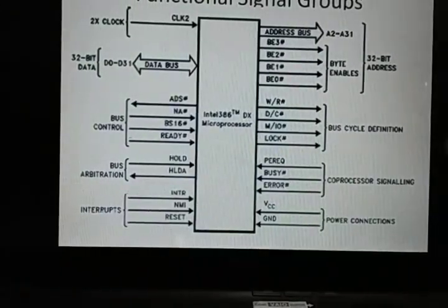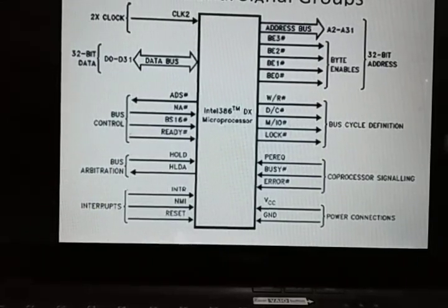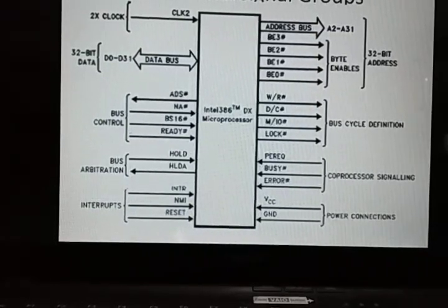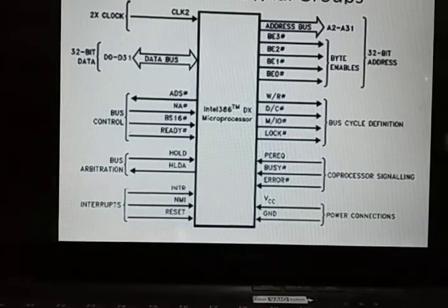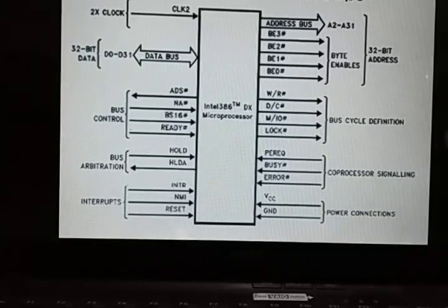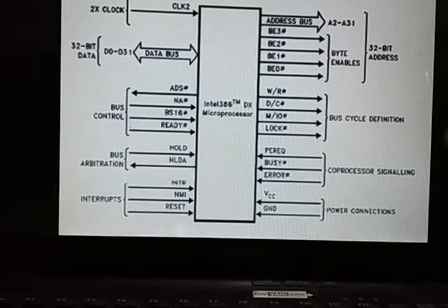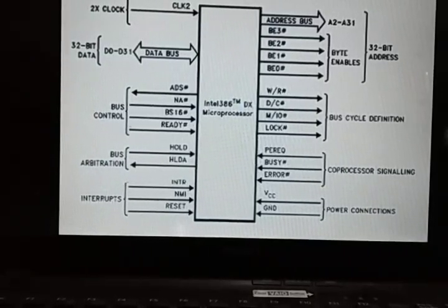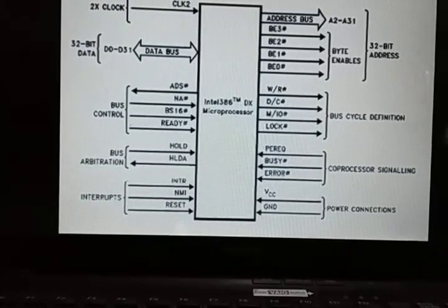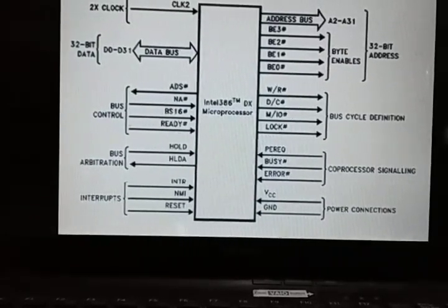So these signals are generated internally by the microprocessor from address A1 and A0. So A1 and A0, basically these address lines we are using to select the signal from B0 to B3. The 32-bit data bus supported by 80386 and the memory system of 80386 can be viewed as a 4-byte wide memory access mechanism. So the 4-byte enable lines B0 to B3 may be used for enabling these 4 banks using these 4 enable signal lines. The CPU may transfer 1 byte, 2 byte, 3 byte and 4 byte by using the bus enable lines.